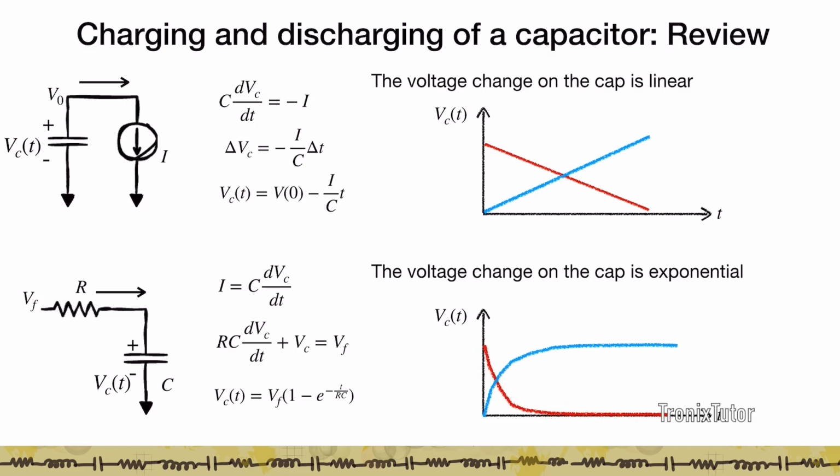If you look at transistors, we will use both these models, but in most cases we will say that the transistor discharge and charge up looks like an RC network. And later on we'll develop an RC delay model for the transistor, which will be used to analyze delays in digital circuits. In an RC circuit, as all of you know, this time is a very critical time, known as the time constant of the circuit, and it dictates the speed at which the capacitor is charging up or discharging. So this time constant RC is a very critical time constant in the charging and discharging profile.